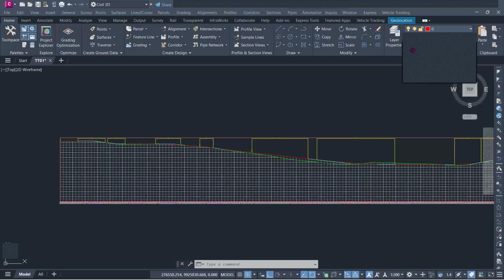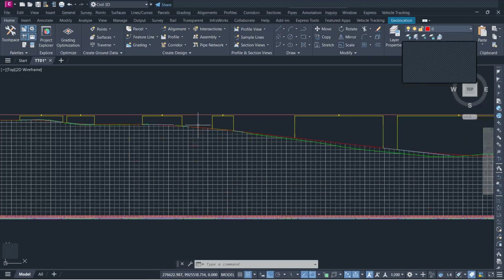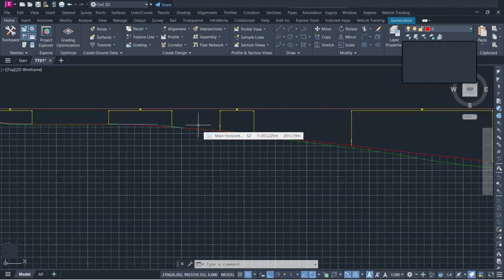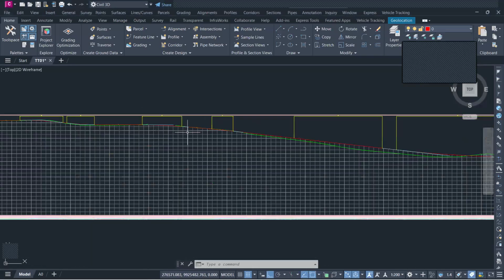We had to do an appraisal and even another appraisal, because at such a section you need to do a lot of rock fill to stabilize the ground. So even as we do the vertical alignment design, it is important for you to keep in mind that it changes when you go to site. There is a possibility, so you don't lock your mind.